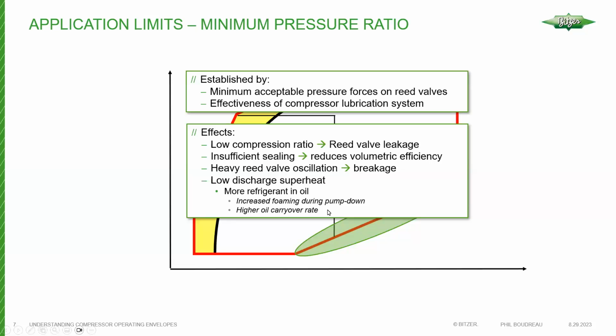In this case it also tends to contribute to a higher oil carryover rate, especially when the oil foams up on you and now you've got a crankcase full of foam. A lot of that foam is just going to get pumped out into the system. And sometimes this is mistaken for a compressor problem when in fact it's a lubrication problem.